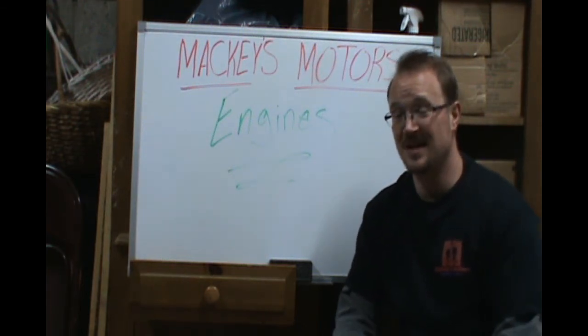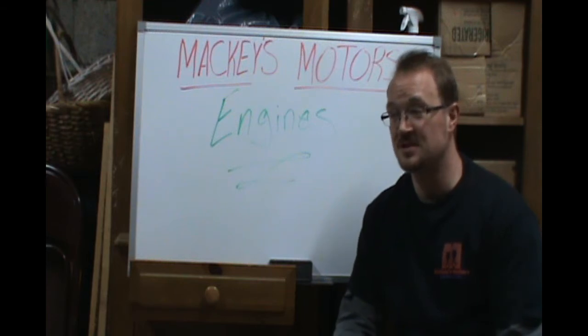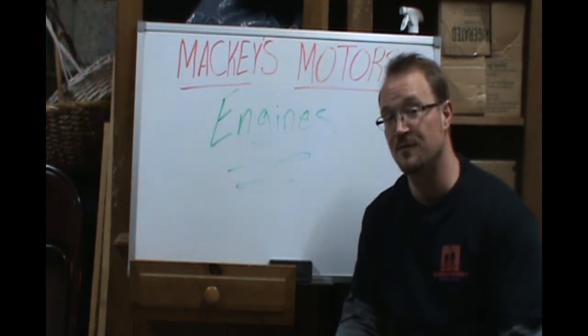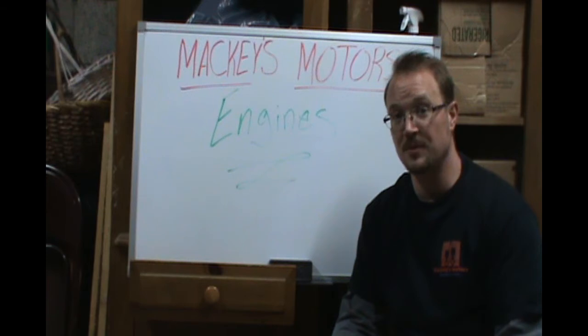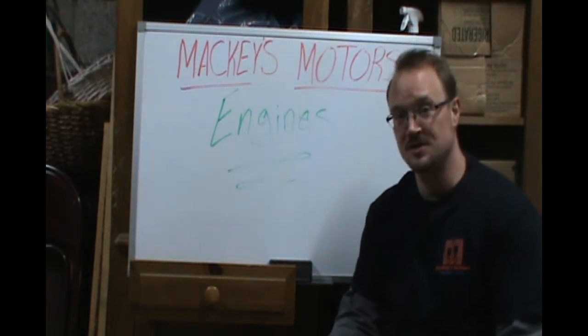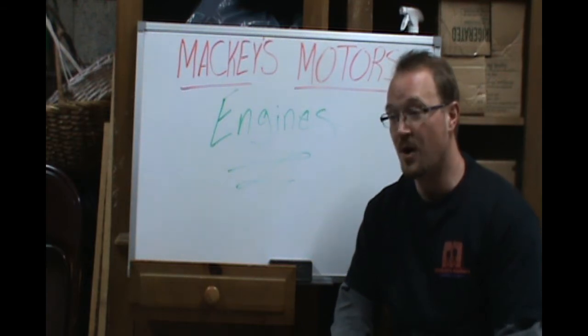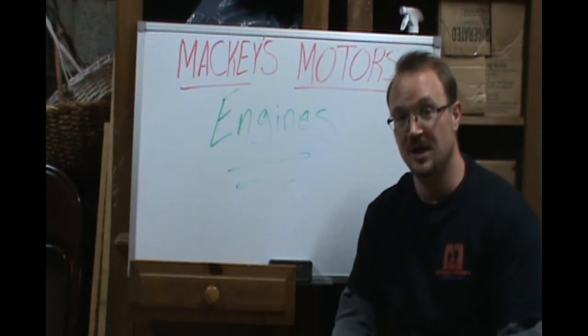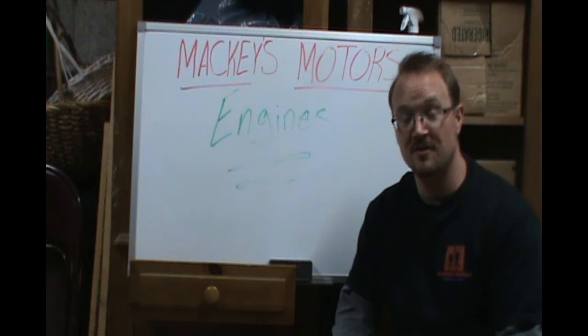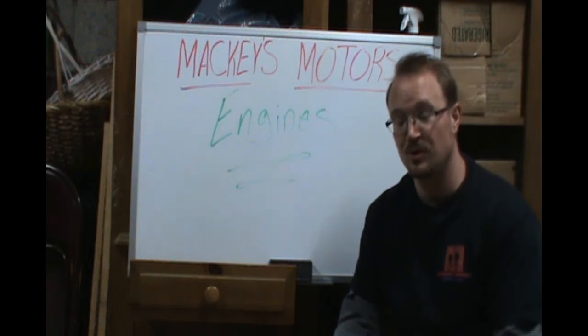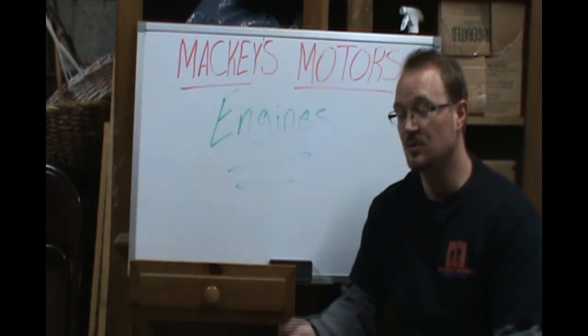And once it's inside the engine, it's tougher for the engine to burn. It's tougher to get that clean air mixture with your fuel, and you're no longer running properly. And what that can cause in the future is problems with your exhaust system, your catalytic converters, problems with too much heat, which would cause rust and corrosion on manifolds and other components like the nuts and bolts that secure those things, and so on and so forth.